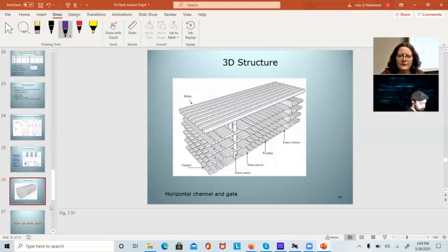So when I'm dealing with this 3D structure, remember these are separate wafers here. So this is like silicon wafer 1, this is like silicon wafer 2. I put the through silicon vias coming down through there and some kind of interposer that makes sure that they all get connected together. I can put drain contacts, I can put bit strings going down, I can put word lines going down. And then this 3D NAND becomes just a bigger NAND flash. And this is how they're dealing with the density problems.